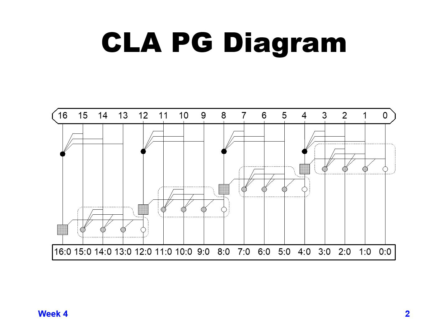Now at bit 12 we have a normal carry skip at bit 16, but then we have the 3 carry look ahead complex functions at bits 13, 14, and 15. The slowest and most complicated one of those is going to be at bit 15 because you have the most inputs. And the more inputs, generally a single stage is going to be slower. So our slowest path is going to be through bit 15.